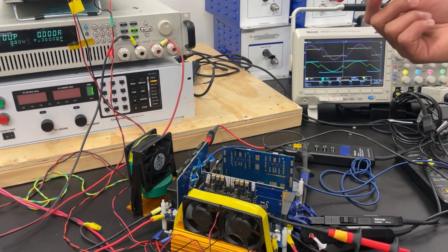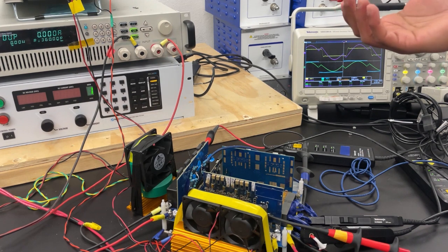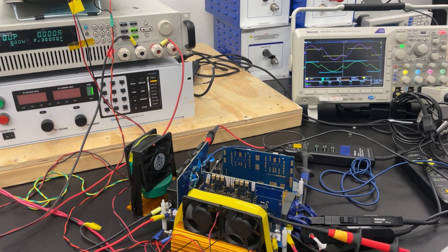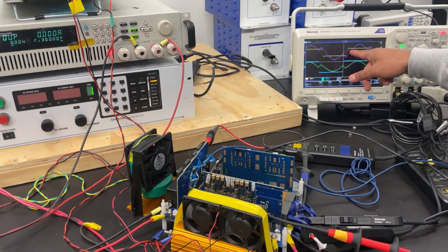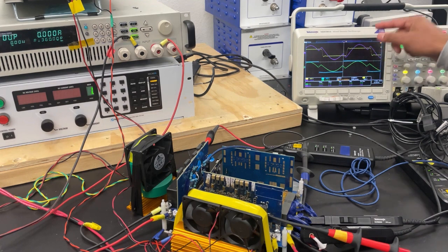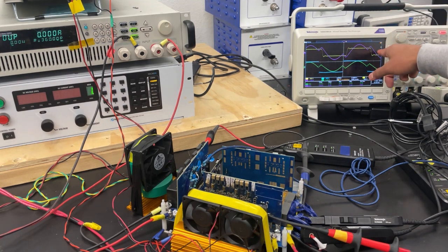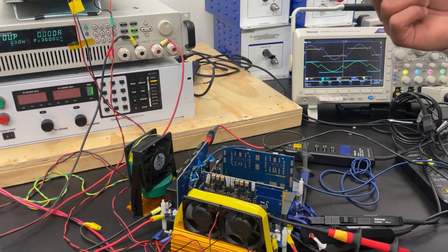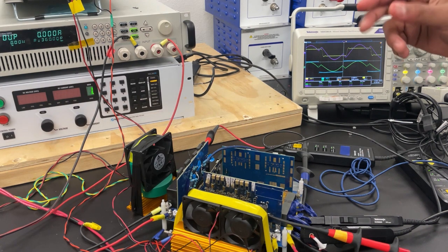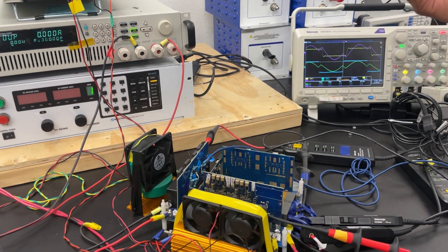The advantage of ZVS turn on is that with a gallium nitride device, the turn on loss is almost minimized. It almost becomes negligible. That is imperative in modern power converter systems, to achieve ZVS or ZCS conditions. So in this case, we are achieving a ZVS condition. Similarly, on the other transition, when VP goes from plus Vin to minus Vin, we see that the current is positive. This positive current, because of its orientation, is able to discharge the output capacitors of switches S2 and S3, and that also ensures ZVS on those two devices.